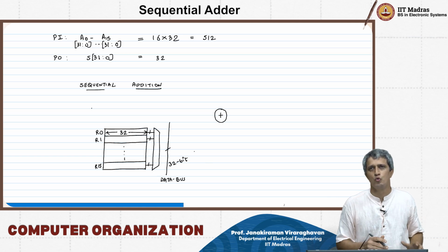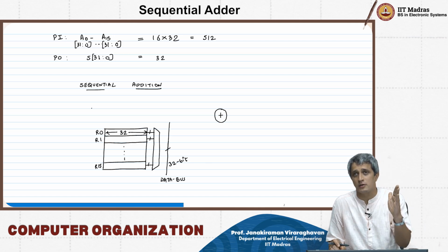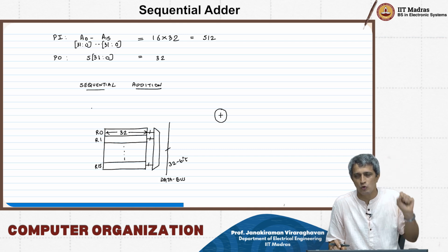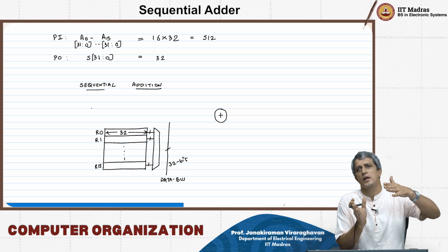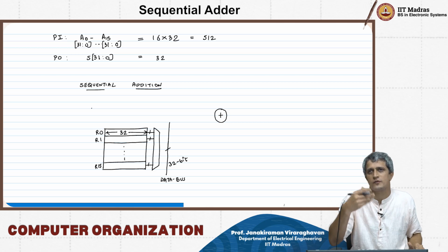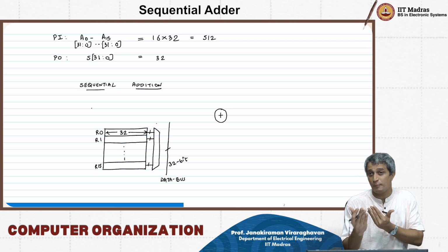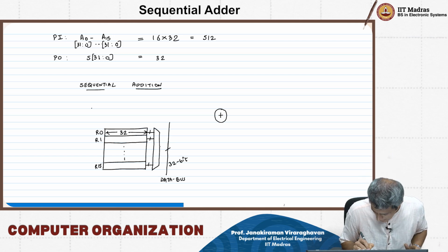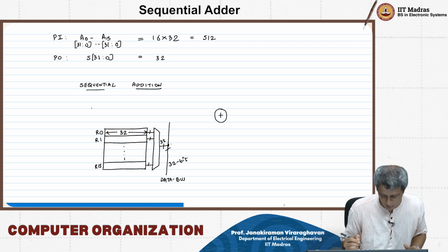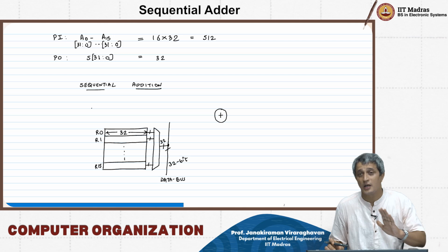And I have a huge multiplexer which is going to do this. Every bit, for example register 0 bit 0 to register 15 bit 0, will get multiplexed in a 16:1 multiplexer, and you will get the 0th bit from there. Likewise first, second, third, all the way to number 31. So this is just a bunch of parallel multiplexers, and I'll get an answer which is 32 bit, which I just connect to this data bus. How this is implemented we'll look at a little later.